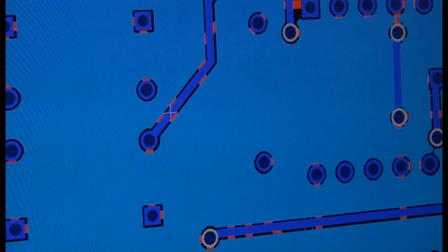We've actually wired this blue area to ground. So all these connections are potentially very close to short circuit. So when you come to manufacture them and assemble them and solder them, you find that you get short circuits all over the place, and it's usually due to this gap.